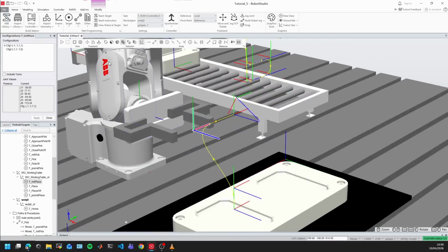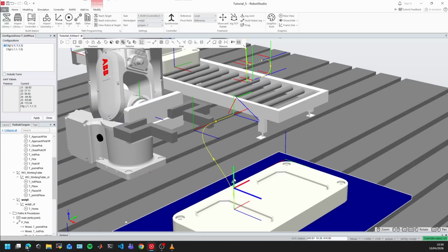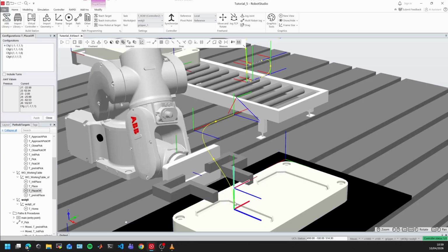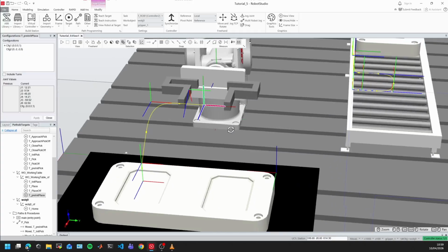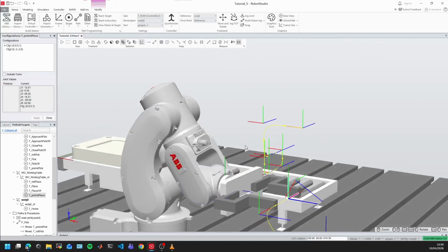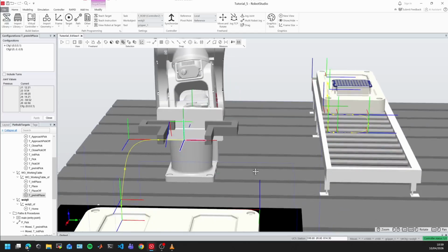The same thing in here. Look at this. If I select this one, no, I prefer the previous one so that I don't rotate. This one the same, that one the same. So I keep repeating the steps, and the configuration seems to be fine. Just beware, because the configuration that ABB selects automatically can be random. Luckily for me, this selection was good, but for you, it might be another selection. So you have to properly select the configuration.